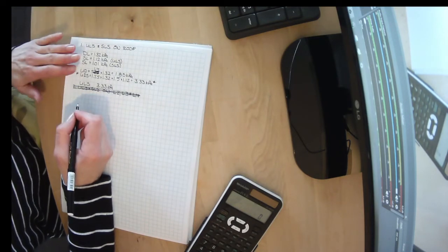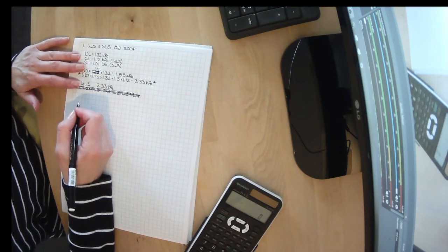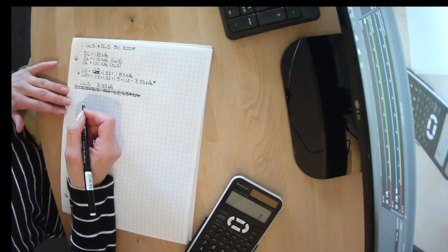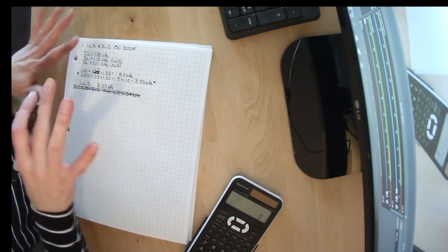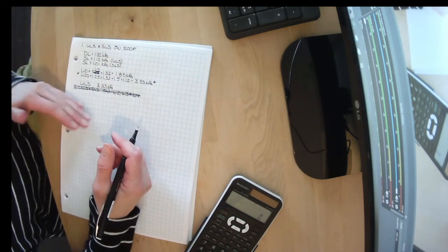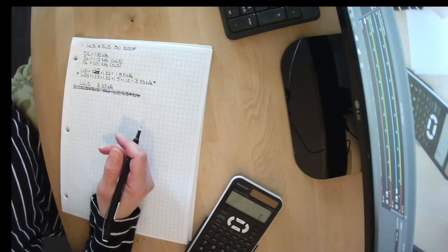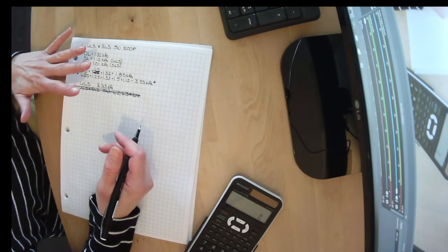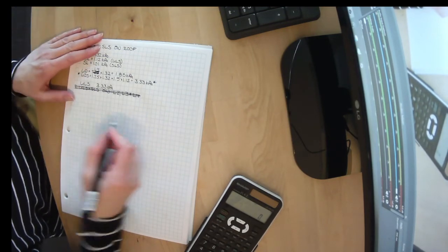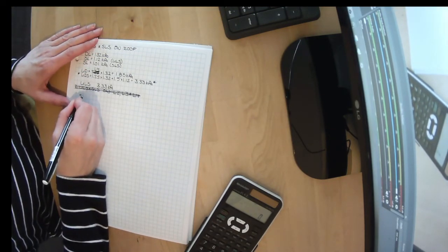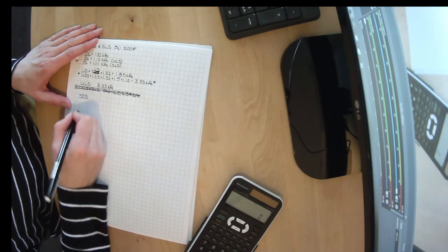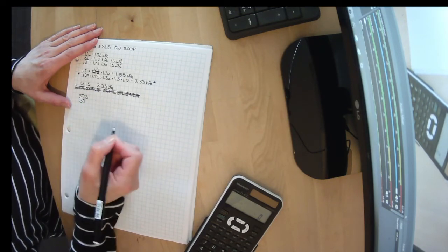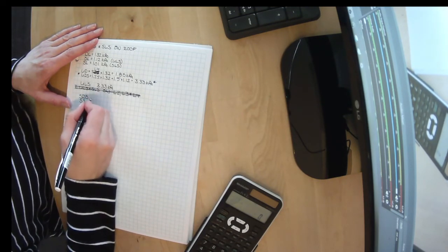tracking both. Strength, we're worried about the worst case. Stiffness or serviceability, we're comparing them to different things. It will become more clear next term when we have that thing to compare them against. But right now, you have to trust me that we have to track both. We are tracking serviceability dead and snow and serviceability snow all by itself.